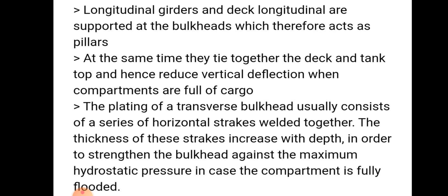The plating of a transverse bulkhead usually consists of a series of horizontal strakes that are welded together. The thickness of the strakes increases with depth in order to strengthen the bulkhead against the maximum hydrostatic pressure in case the compartment is fully flooded.